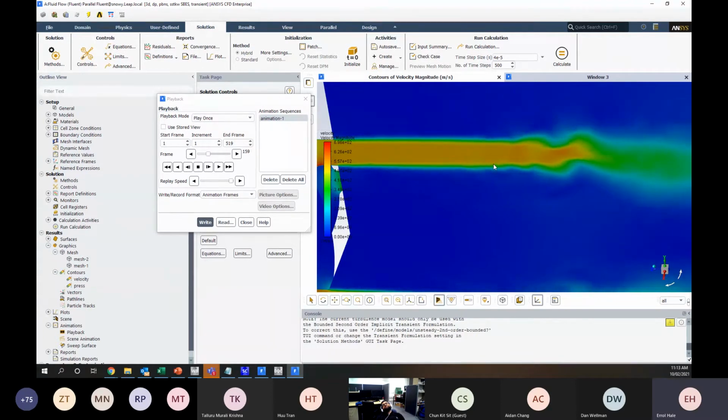So we won't necessarily pick up that kind of oscillation if we're just using a RANS model alone. And it's really important for us to pick up this oscillation because a lot of the sound that we have found to be problematic for the clients using the sleep apnea mask is coming from aeroacoustic effects. So in order to get aeroacoustics, we need to be using higher order turbulence models. That's the moral of the story here.